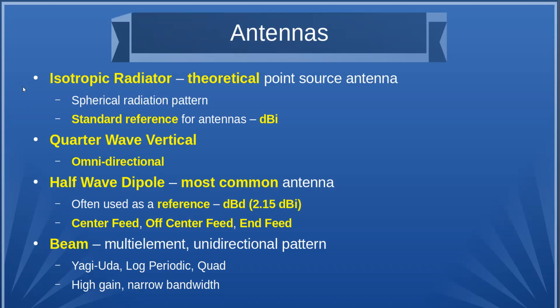All harmonics. Yeah, that's one of the benefits of an end-fed: you don't have to do a lot of traps and other things. If you had an 80 meter end-fed, which would be 3.5 megahertz, you're going to get 7 megahertz, 10 megahertz, whatever, 4 times 3.5, on up.